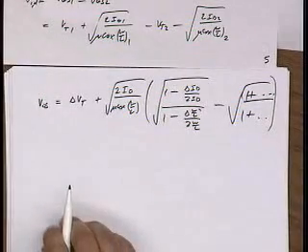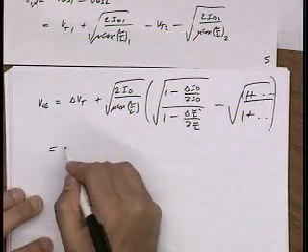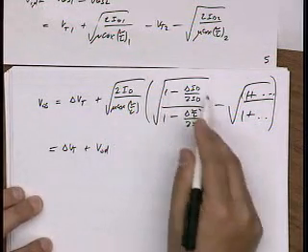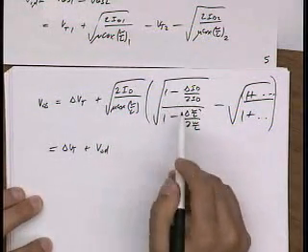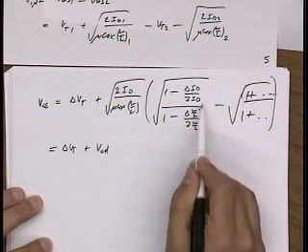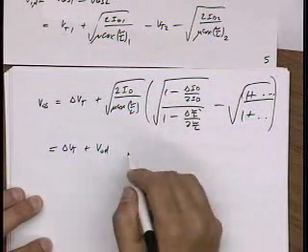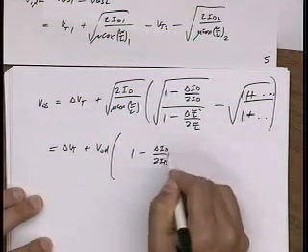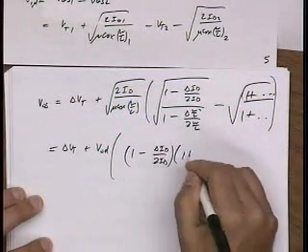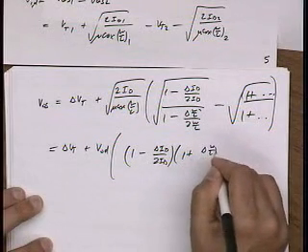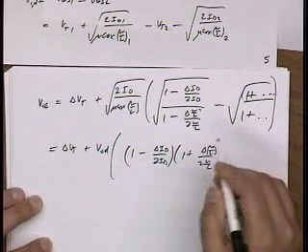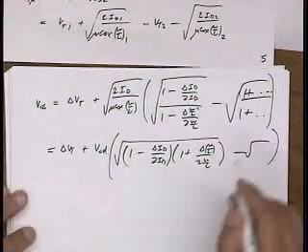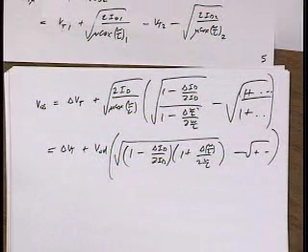And this, of course, is the overdrive voltage for square law. Simplifying this term, this is 1 plus x, and so what happens is I get 1 minus delta ID over 2ID, 1 plus delta W over L over 2 W over L, minus the same thing, plus minus.